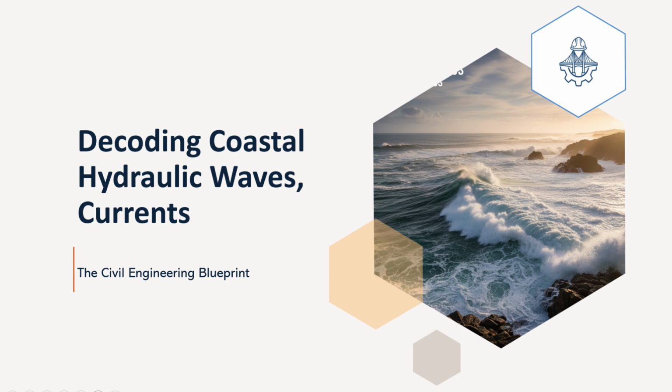This fundamental theory, it goes by a few names. Small amplitude wave theory, or sometimes Airy wave theory, honoring George Biddell Airy, who published its correct form back in the 19th century. It's a cornerstone for good reason, providing the basis for many, many modern coastal engineering calculations. And what's the core assumption that makes this theory so powerful, yet also gives it its linear name? What simplification makes it, well, solvable? It's based on the key assumption that the wave amplitude is small compared to both the wavelength and the water depth.